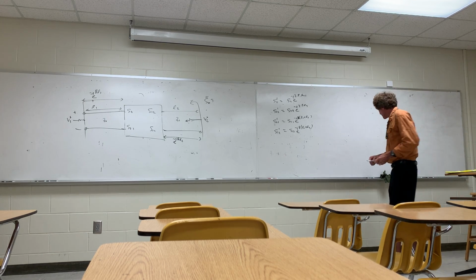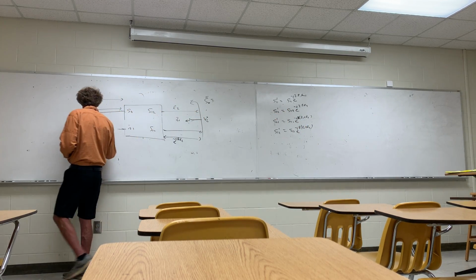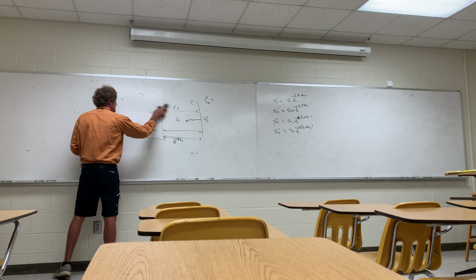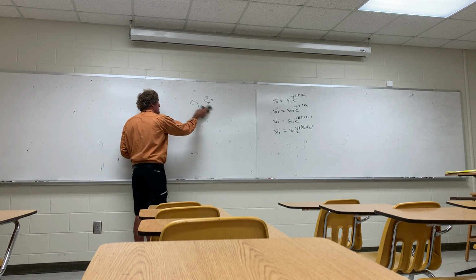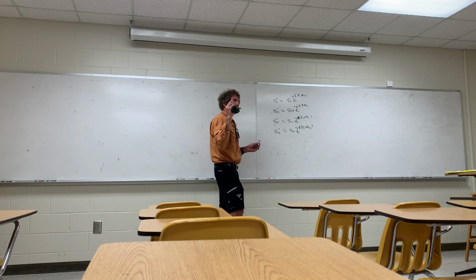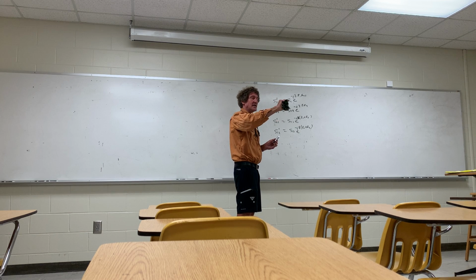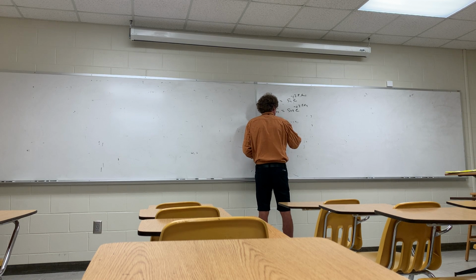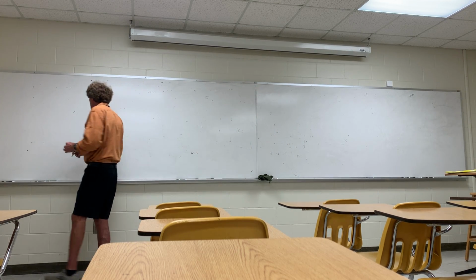Next thing is circulators. Now, circulators are real important when you have things called transceivers. If you're going to use an antenna for transmission and reception, like you do in radar all the time, then you have to have something that will quickly change the actual electrical connectivity of the antenna to the system, because if you don't, then you'll destroy all sorts of electronic equipment. If you try to listen when you're transmitting, you'll blow up that unit.